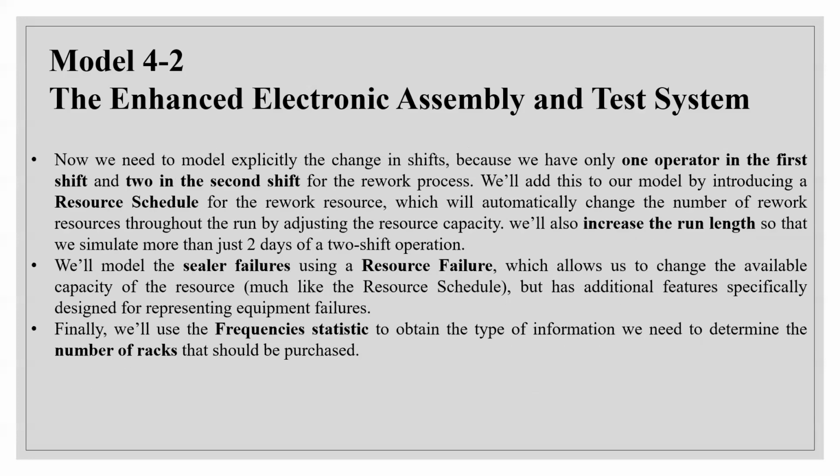So now we need to model the changes in shifts because we have only 1 operator in the first shift and 2 in the second shift. For the rework process, we will add this to our model by introducing a resource schedule for the rework resource, which will automatically change the number of rework resources throughout the run by adjusting the resource capacity. We will also increase the run replications so that we simulate more than just 2 days of a 2-shift operation.